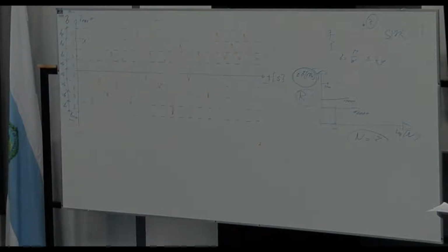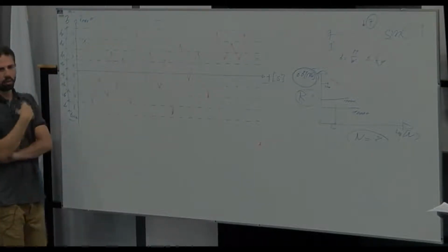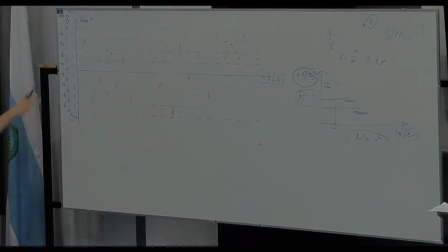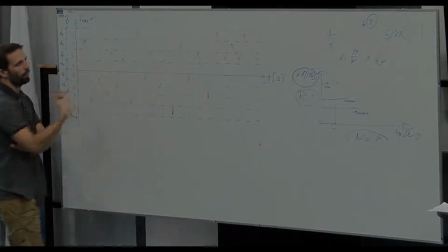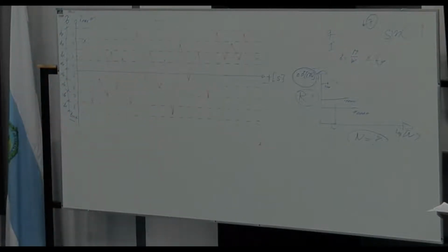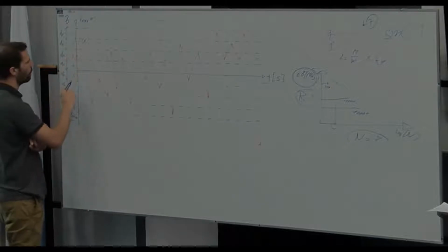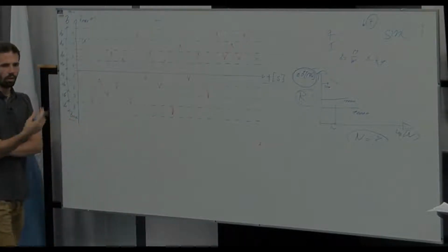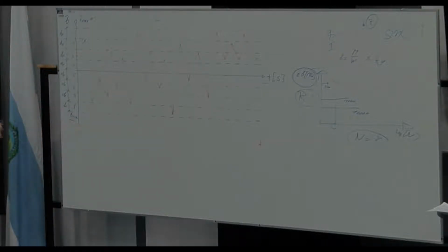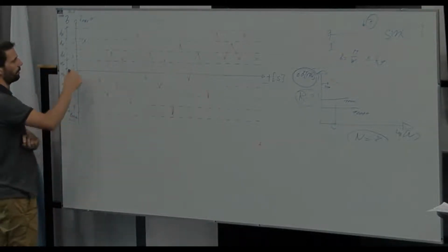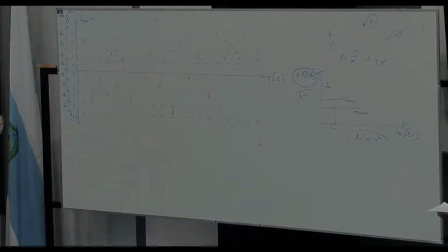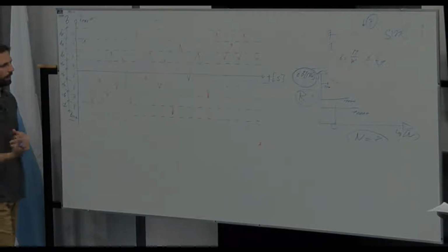At the end you have no information at this level about the stresses which are really acting. You just know the class of your peak, but you lose the information on the stress amount. This is something you have to take care of in the evaluation of the histogram at the end.